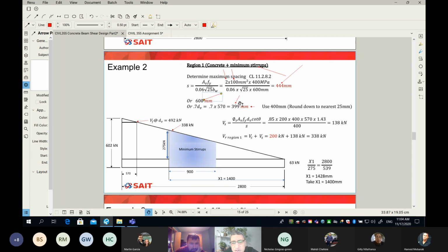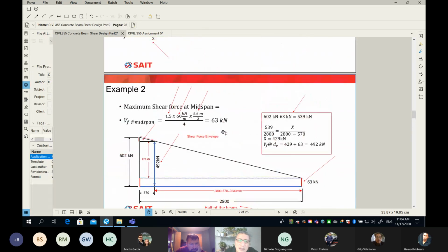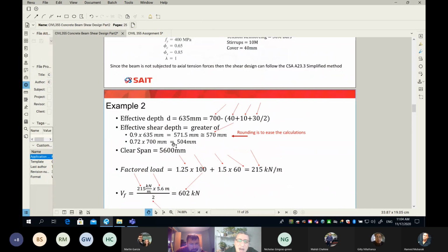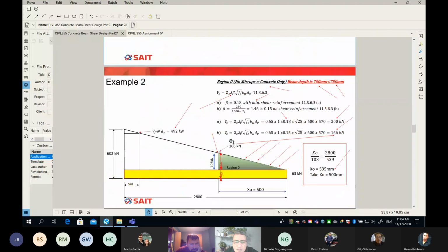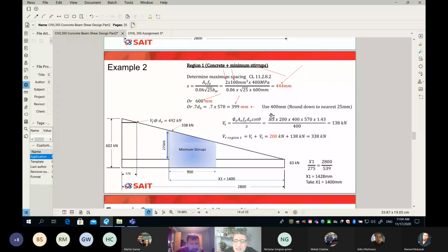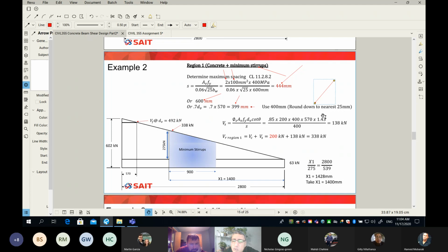So when I picked the 399, I know some of you will say, Tahir, if we round to 400, it means we're violating the 399. I can tell you, I already rounded here. If you go back to the 570, my d_v was not really 570. If you remember, my d_v was 571.5, so we're within a fraction of a millimeter even. That's why I'm not going to go to 375. I will just say this is roughly 400. But in general, I give you the rule here: you should round down to the nearest inch, 25 mil.